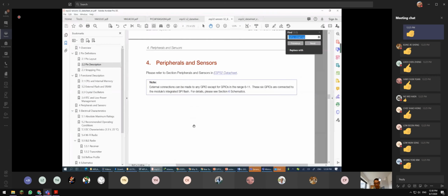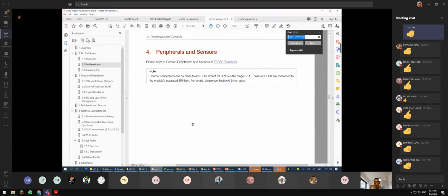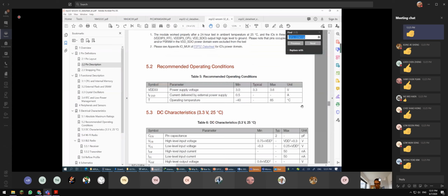Why? Because in future you might develop your own development board. Of course, the ESP32 development board is very cheap in the market, but you must remember you can make it cheaper, and it's made in Malaysia, and have more features. You can always put in more features. For example, what are the problems in this ESP32? They don't have some indicator, they don't have I2C extension, all this extension board. So you can build all in one, just for sharing.